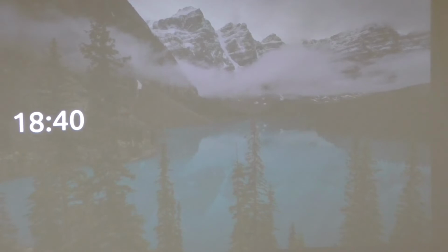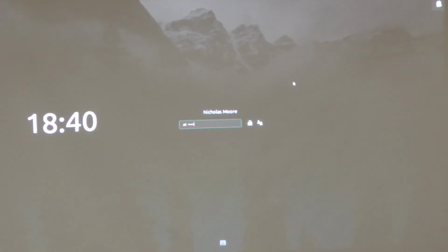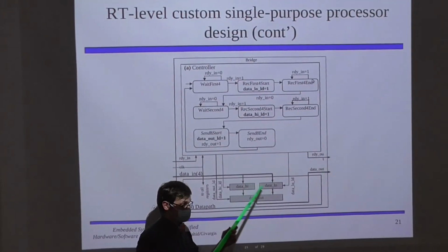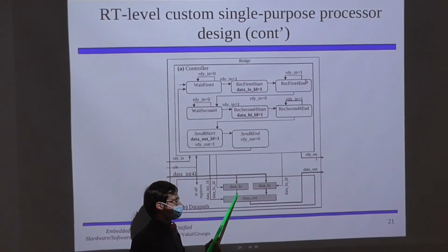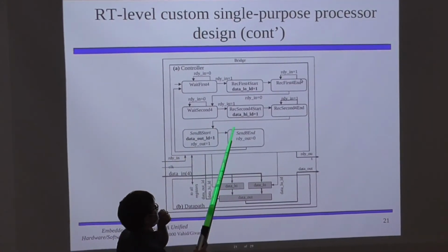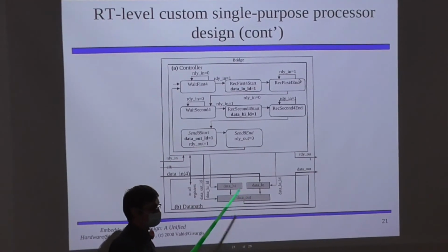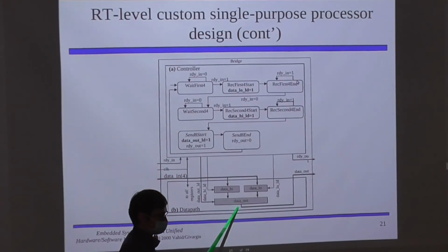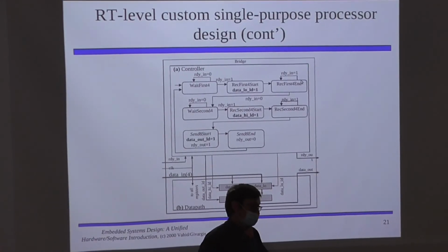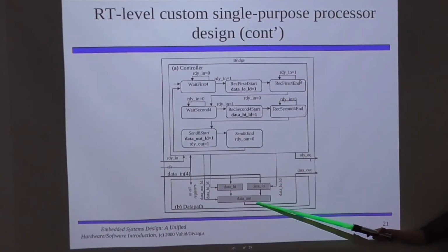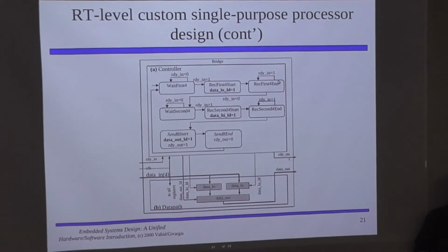The reason that I didn't catch this while I was doing the lecture itself, but the reason that you separate that, right? You don't want the outputs to be derived directly from these registers only, because these outputs change during a load operation. The way that this is currently configured, this data out value remains stable until this state. So all through this, it hasn't changed or been modified, and anybody relying on it can rely on it not changing. The whole purpose of the ready out signal is to indicate when that value is ready, but it's also good to maintain stable values from a good design perspective.